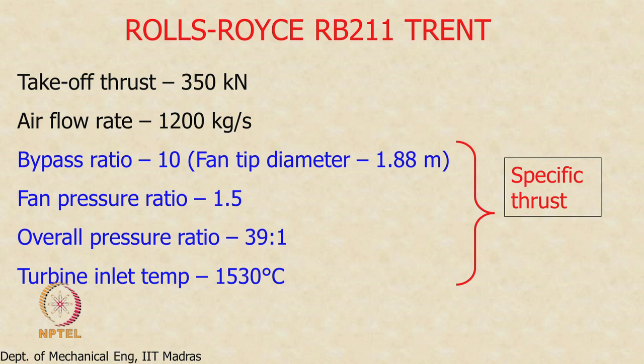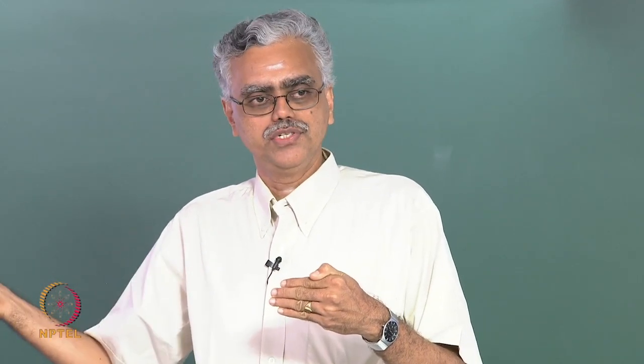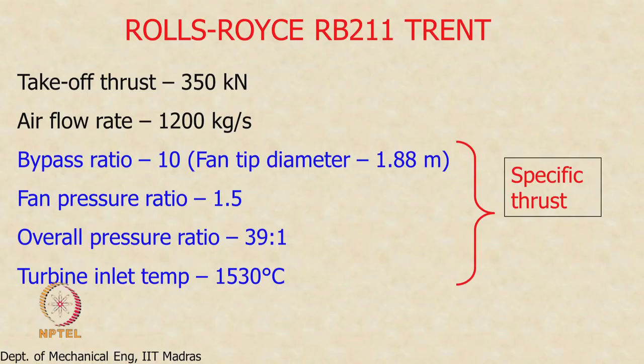What is challenging and interesting about this is this temperature of 1500 degrees Celsius. If you recall from our earlier discussion, we showed the engine, right. So the air goes into the combustor where we raise the temperature to about 1500 degrees Celsius, then it comes to the high pressure turbine, right. This temperature is about 200 to 300 degrees Celsius above the melting point of the blade metal, okay, and still the blade does not melt. That is what is challenging and interesting about this technology, that the engine can operate at temperatures which are about 200 to 300 degrees Celsius above the melting point of the blade metal and still continue to operate without any problems.